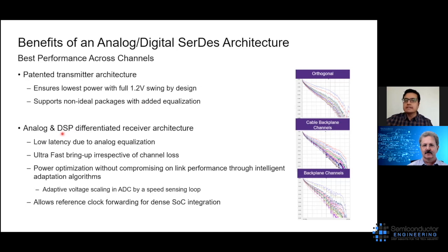If all the filtering is done digitally, it adds latency in the data path. So there's a fine balance that needs to be done on analog, because analog does real-time processing. It doesn't add latency. Also, there are requirements with respect to bring up of these SerDes, because these are used with SSD these days. And this also calls for a balance between analog and digital implementation.